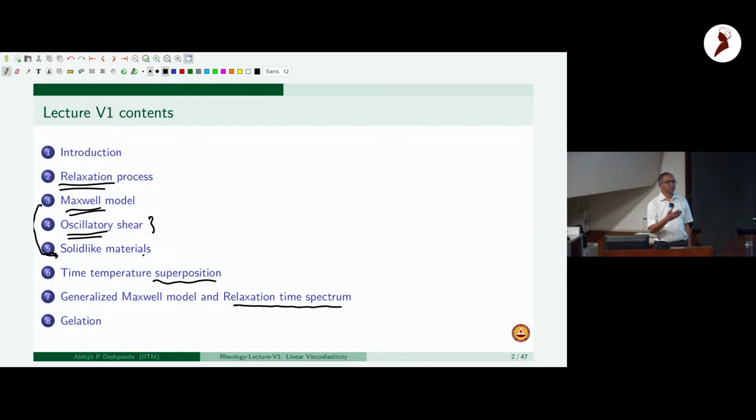So for a product that I am designing for 25 years, I can test it at higher temperatures and then confirm that it is not going to degrade in 25 years. This is only possible if there is an equivalence between time and temperature, and that's what we exploit also to gain quantitative material response and characterize its rheology over very wide time scales, even though what's accessible to us in experiments is only a short time scale. So we basically do the testing at different temperatures and then change it to various time scales.